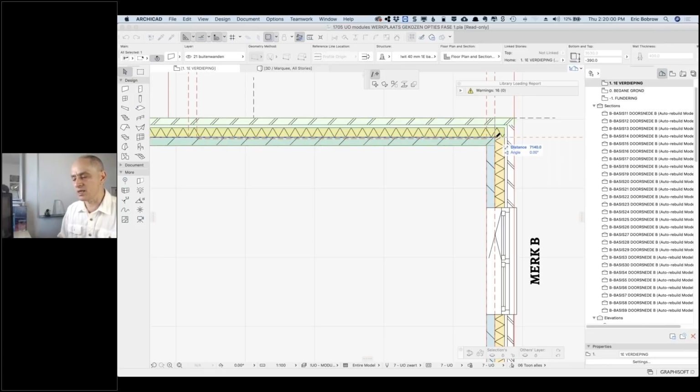Now, the measurement right now is from the other end. In other words, you can see the distance is 7209, so that's 7 meters from the other side of the wall. So we're getting an angle and a measurement from the other side. So you just want to verify that, because if I use the Shift key, well, let's see, sometimes when you use the Shift key, it changes. Yeah, now if I move this up and down, you can see the distance is showing from the new edit origin, which is that corner that it started with.